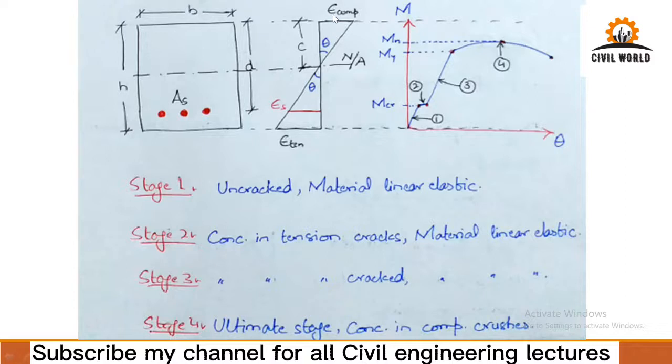Coming to the strain profile, you have some compression strains applied in concrete and some tensile strains applied in concrete in tension as well. You have some tensile strains in steel as well. This is the neutral axis where there are no stresses and strains applied.